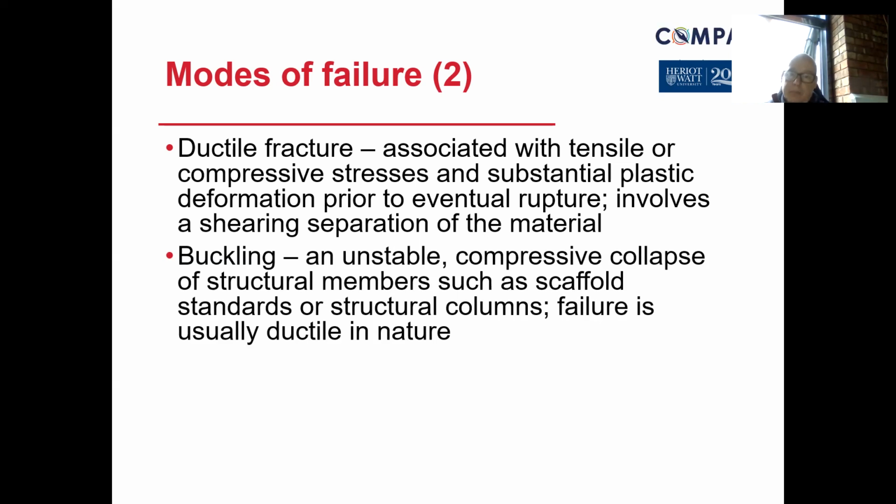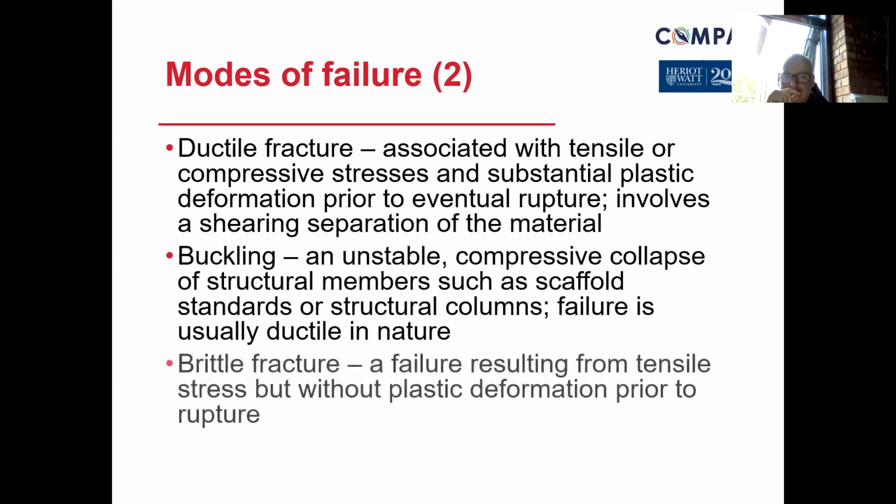so you can put load bearing areas in place. But even so, they will fail after a while, because if you think about the portability of scaffold, it's used on one site for a week, it's taken down, bang, bang, bang, it's put back up again, bang, bang, bang, it's taken down after another week and so on. It's got to have an impact on the ductility, should we say, of the strength of the material, and therefore more likely to fail the longer it's been used.